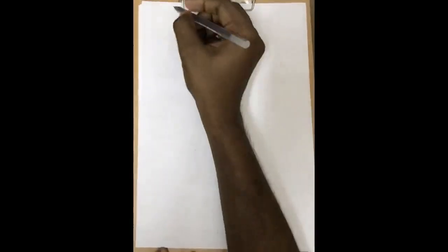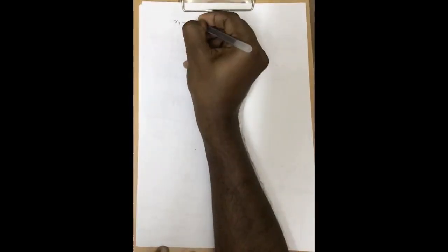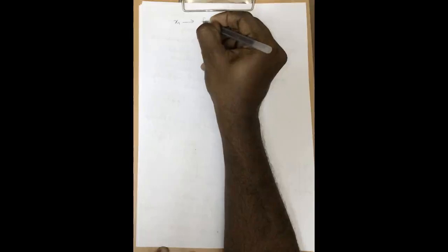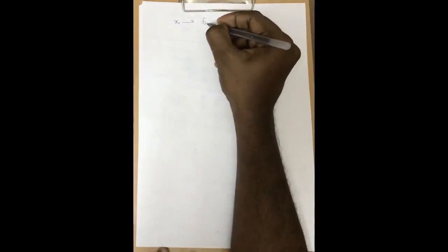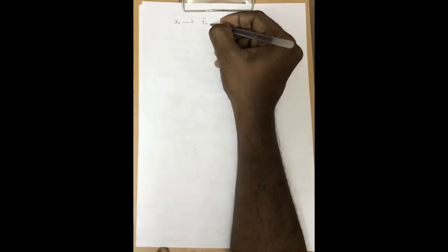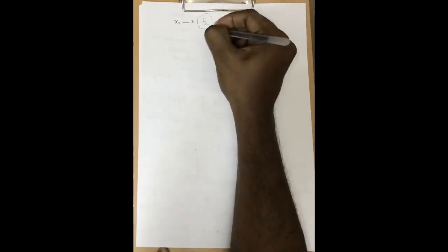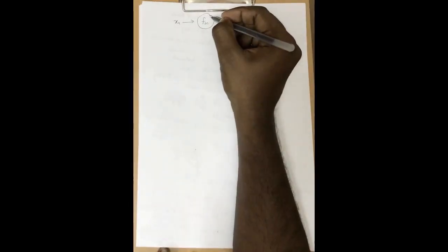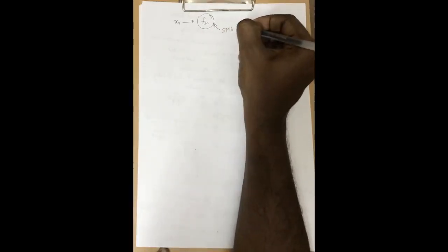So in the above equation of XU, there is a term called Fsc, which is the stress at the level of steel which is subjected to compression. And you need to know this value. Where do you get this value? Fsc, you can get it from SP16 charts, SP16 chart, page number 13,